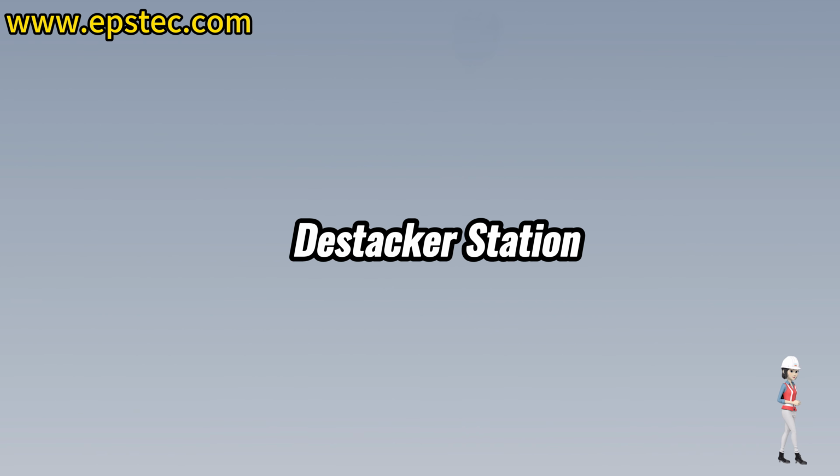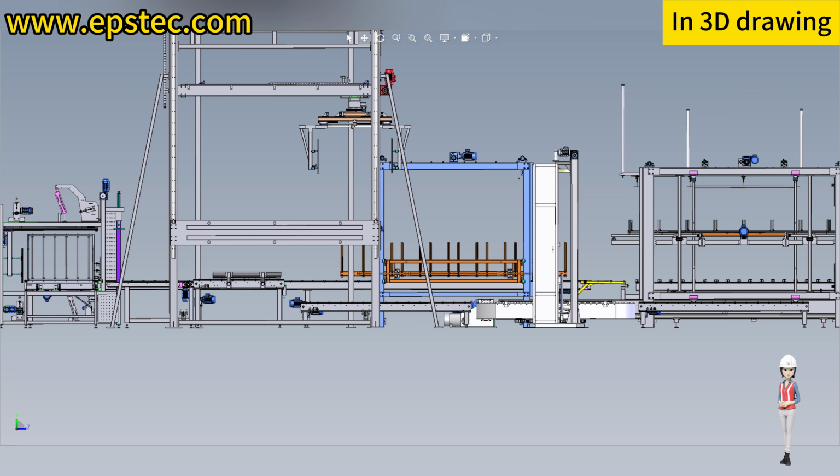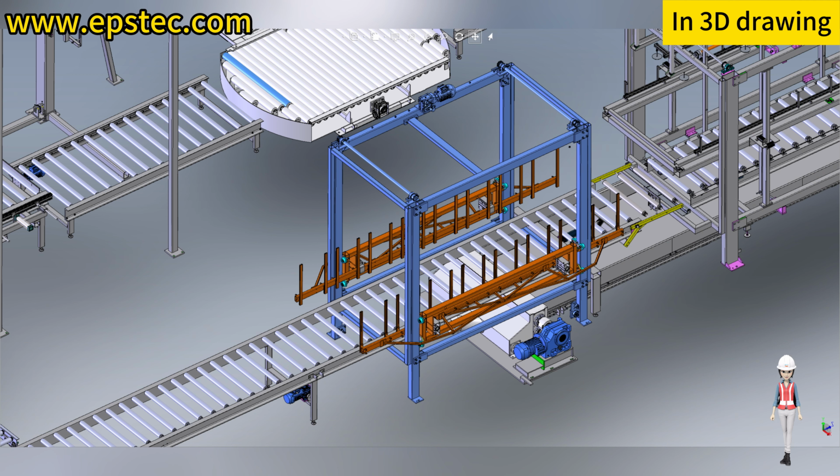Destacker station. EPS boards with a height of 630 mm or 1220 mm can only be destacked once. Only small EPS packages with the main cutting thickness on the lower layers will be processed through the full-side EPS packaging machine. When the small EPS package reaches this photoelectric sensor, the destacker lower conveyor stops.